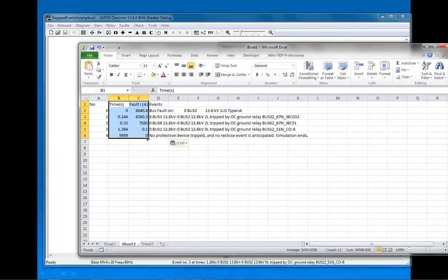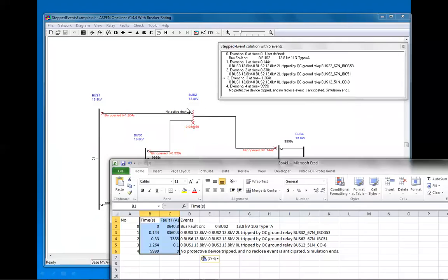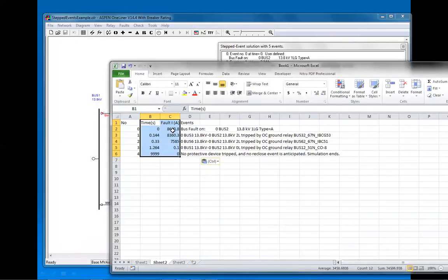And one kind of study where this information becomes quite valuable is the arc flash hazard calculation. If your task is to assess how much arc energy would appear here if you have that fault, it will be proportional to the fault current, and also to how long that current is lasting.